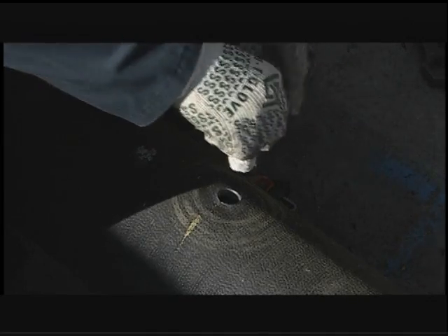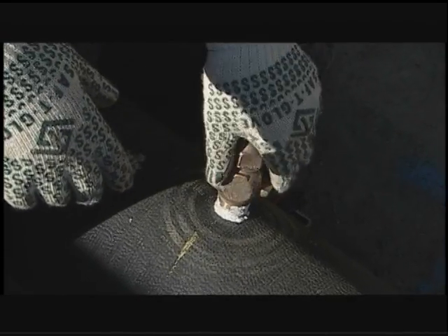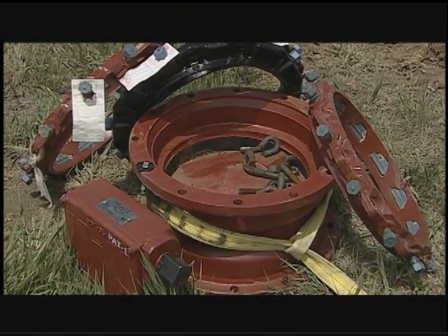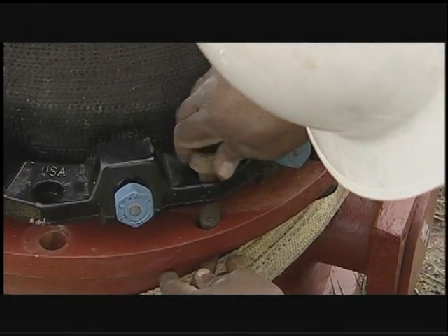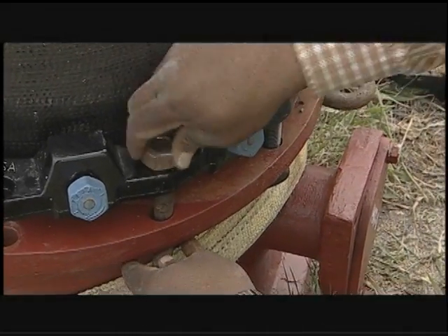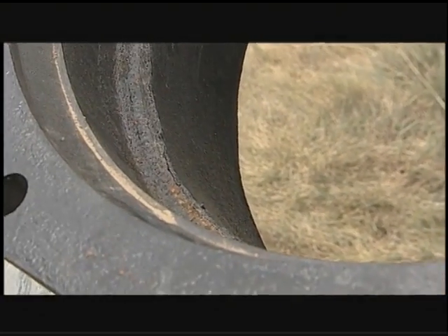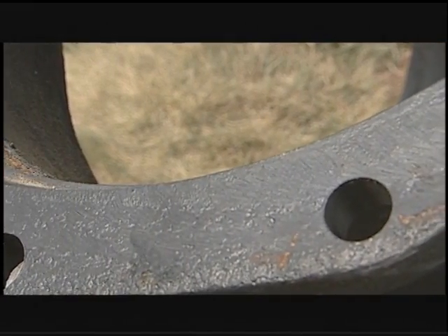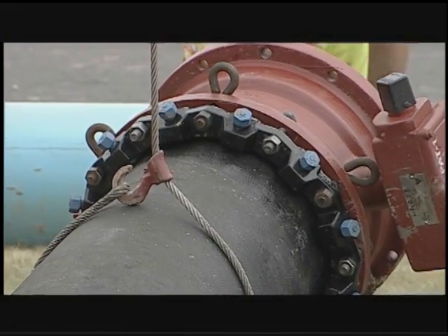The extent of corrosion is influenced by the anode to cathode surface area relationship. An example is shown in this valve. The large valve body is cast iron, which is held together with smaller steel bolts. The two metals are relatively close on the galvanic scale, but the surface area difference between the smaller anode, the steel bolts, and the larger cathode, the valve body, would quickly cause the steel bolts to rust in the right conditions. Replacing the steel bolts with a more noble alloy, which is cathodic to the valve body, minimizes this problem.